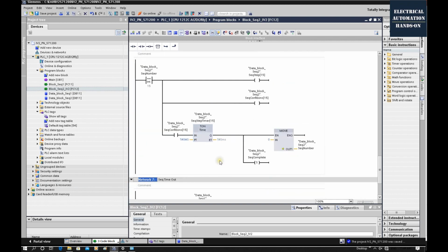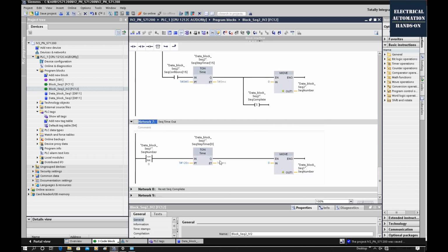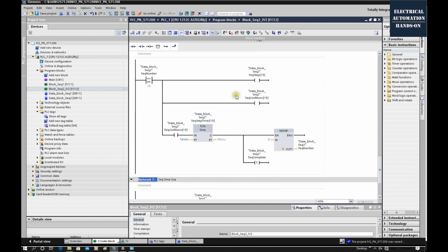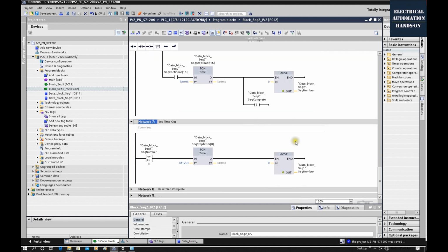If by some reason, for example, communication drop or the camera lock out, if our sequence stops in the middle and without any response, we can set 0 to this sequence, allow this sequence to start from the beginning, and re-trigger the camera. So this timeout will be used as this.